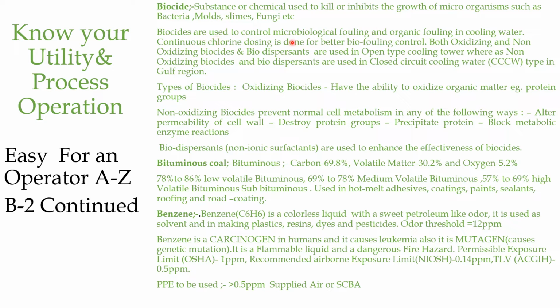Biocides are used to control microbiological fouling and organic fouling in cooling water. Continuous chlorine dosing is done for better biofouling control. Both oxidizing and non-oxidizing biocides and biodispersants are used in open-type cooling towers, whereas non-oxidizing biocides and biodispersants are used in closed-circuit cooling water (CCW) type in the Gulf region.